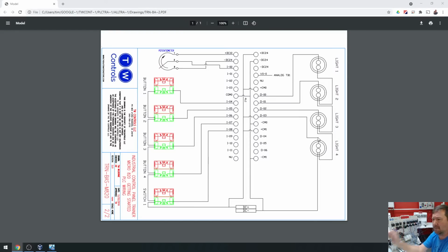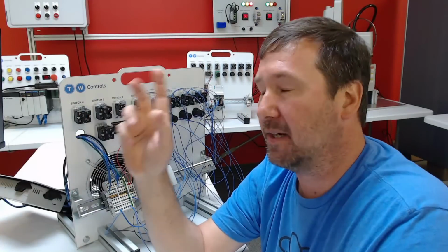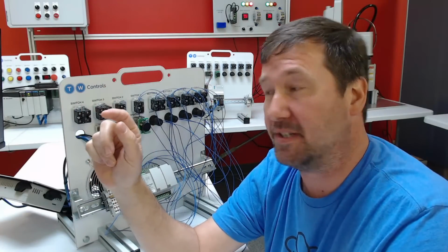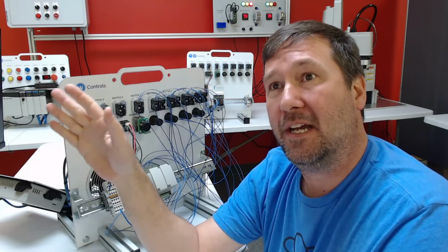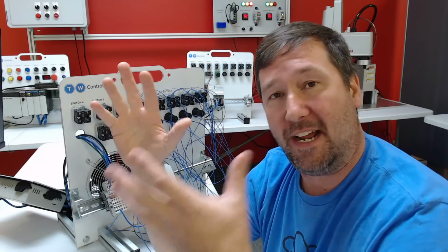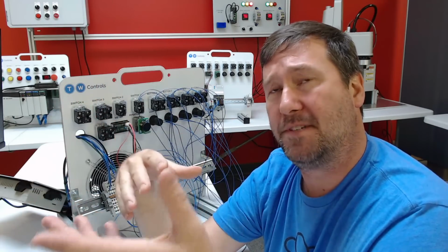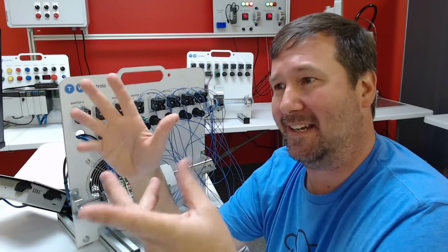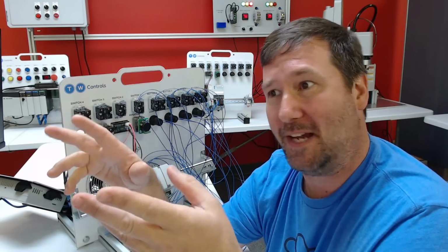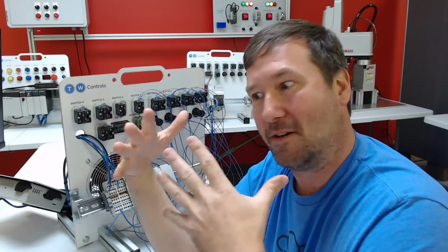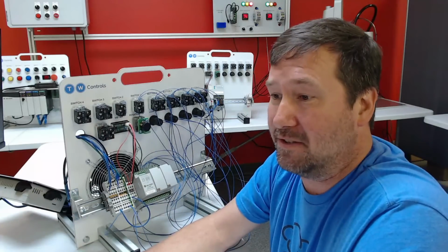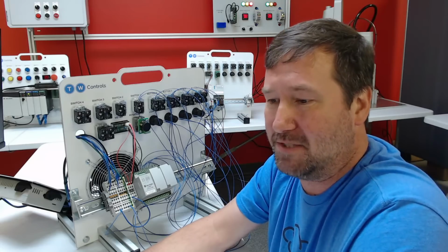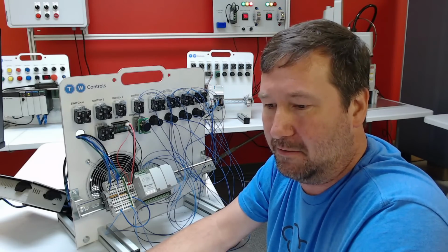Also, Rod, you definitely want to check out that video, because what I just told you about sinking and sourcing is for Allen Bradley. It's also for many others, but there are some PLC manufacturers that do the opposite. Some of them do the opposite on just the output. And if I recall from that video, there was one manufacturer that swapped the terms even on the same model PLC, as you go through the manual. So they are very confusing terms. That's why I always like to see a diagram, just to see how exactly we're going to do it.